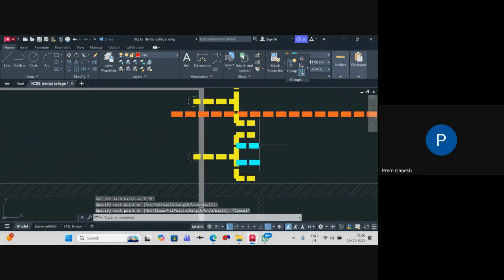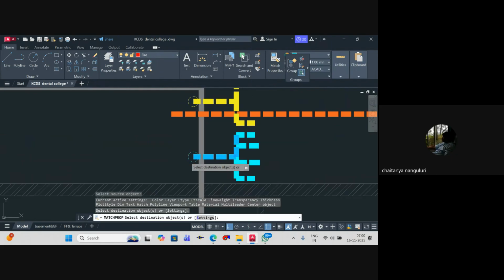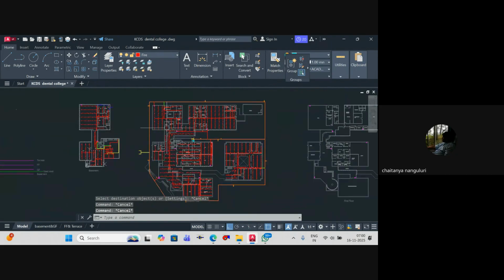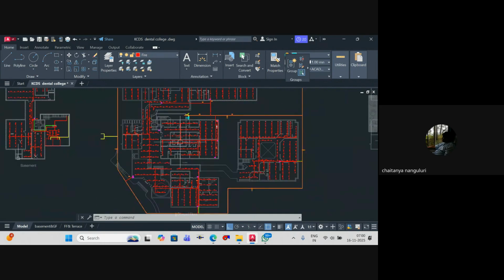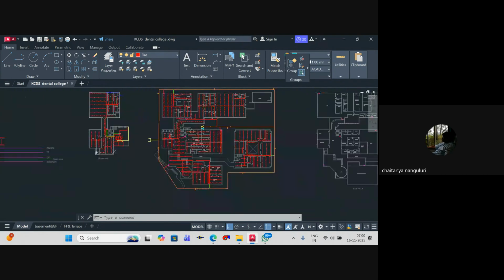Sir, this fire brigade inlet, one is near the sump and one is near the entry. Entry to the site, or entry to the building, sir? Directly to the piping system. That means you can pump water directly into your hydrant system, like your external ring main, so that water can enter into your hydrant or your sprinkler system.